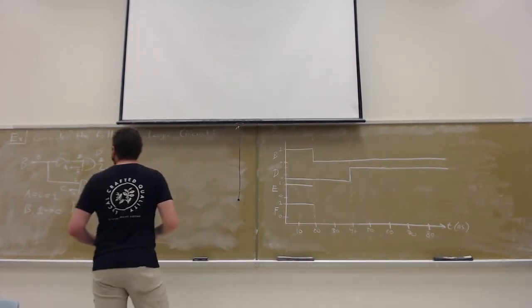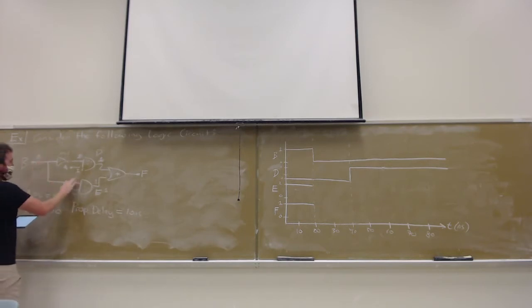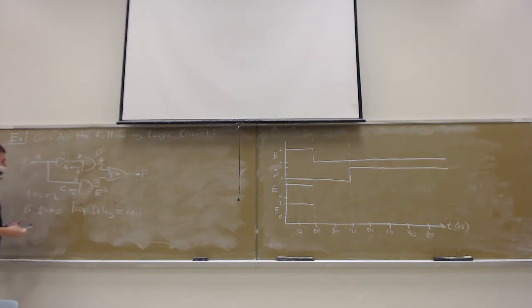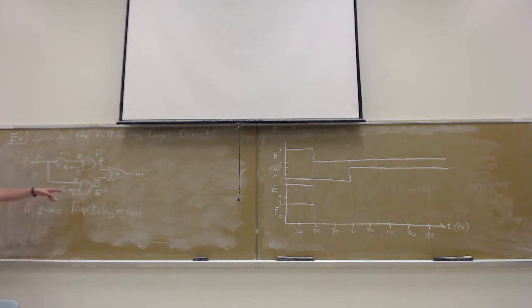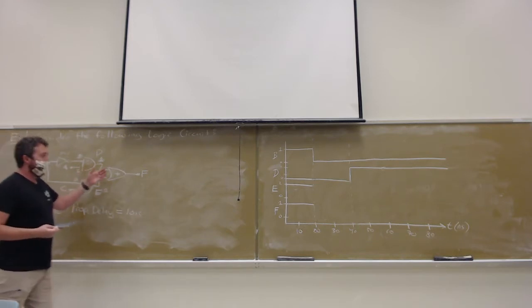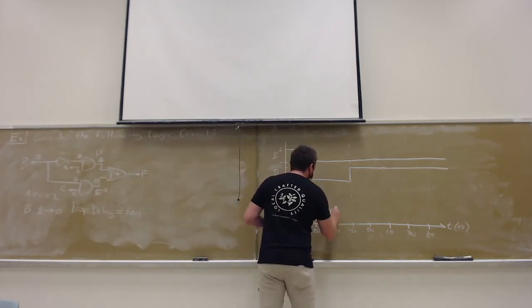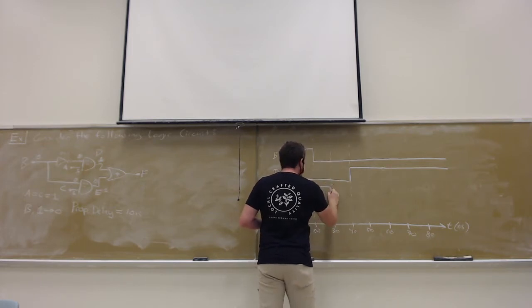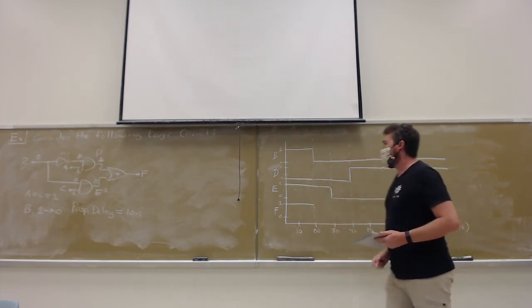And then E. B goes to 0, which means we have 0 and 1, which means that E goes to 0, right? But since there is no inverter here, we just have to pay the 10 nanoseconds delay at the AND gate. It means that E will switch from 1 to 0 at just 10 nanoseconds. Right, it'll stay there forever. Finally,